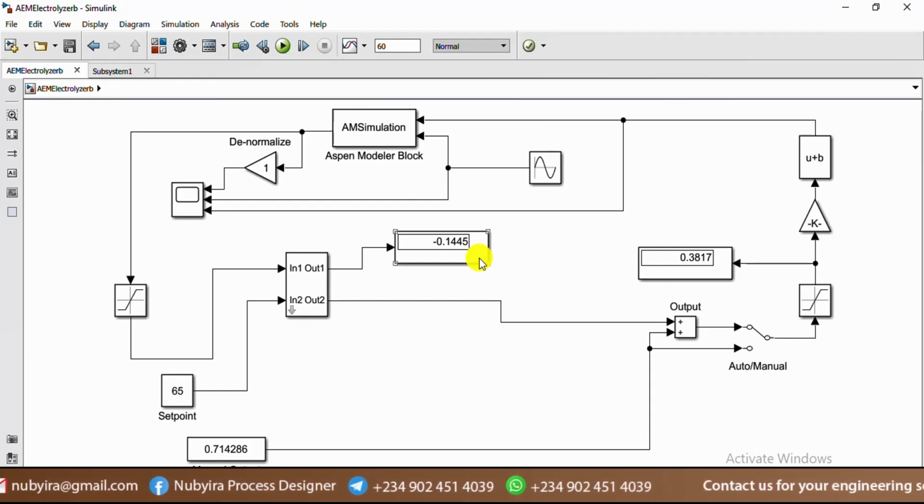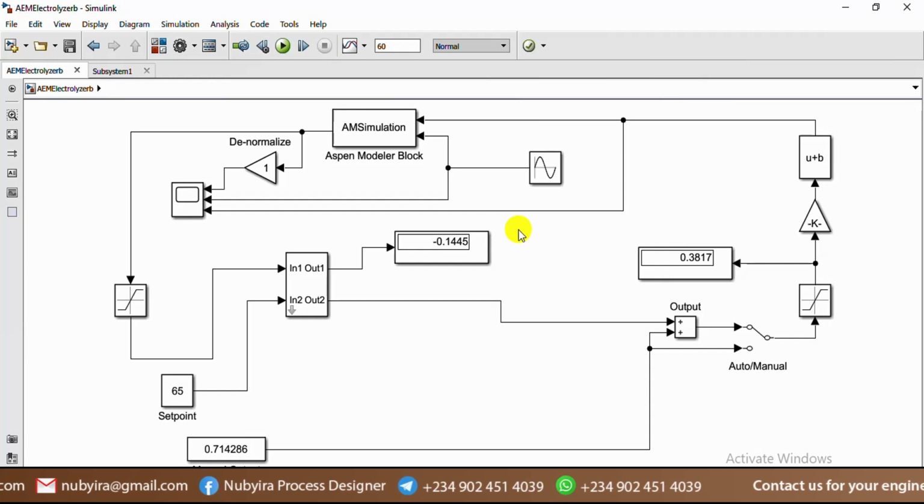The integration of the two software makes it possible to design a rigorous and realistic system, linear system for electrical components and other dynamic systems in Simulink, and the PID algorithm too in Simulink. So you can easily design your own algorithm, do tuning, do more advanced features like dynamic tuning for your discretized system in Simulink.